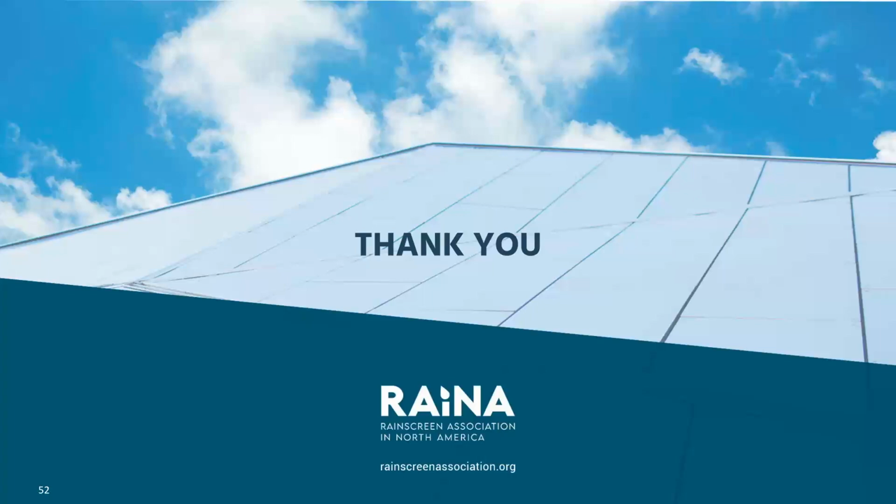Thank you. Before, you mentioned face-sealed eaves, which is barrier eaves, earlier in the presentation. That system hasn't been used, or not as often, in the last 30 years, and has been replaced with drainable eaves, which includes drainage. How would you classify that cladding?